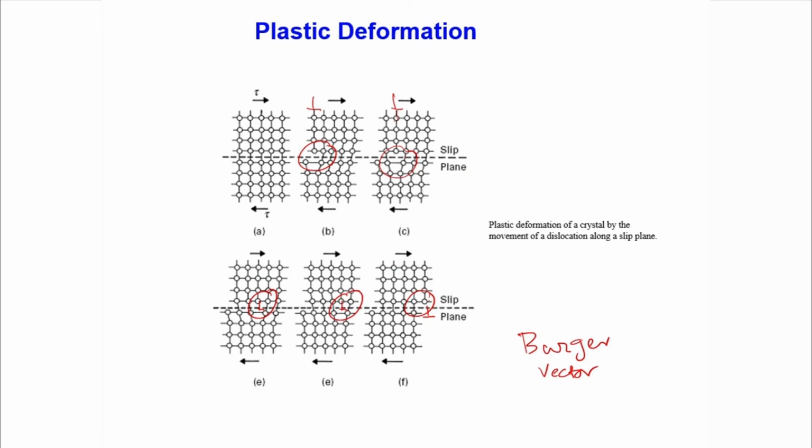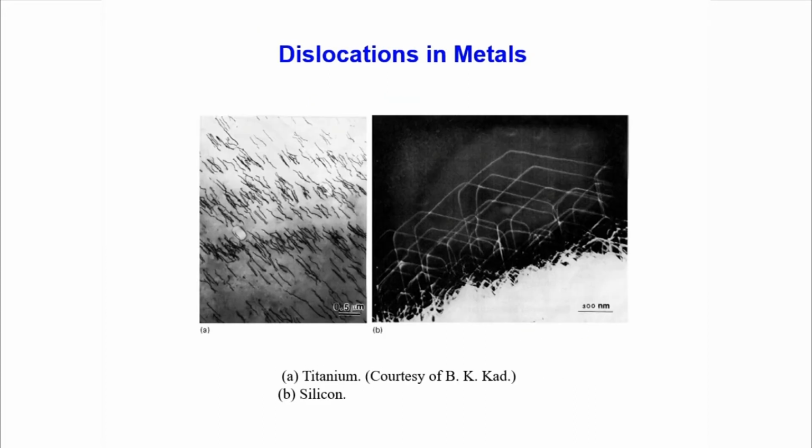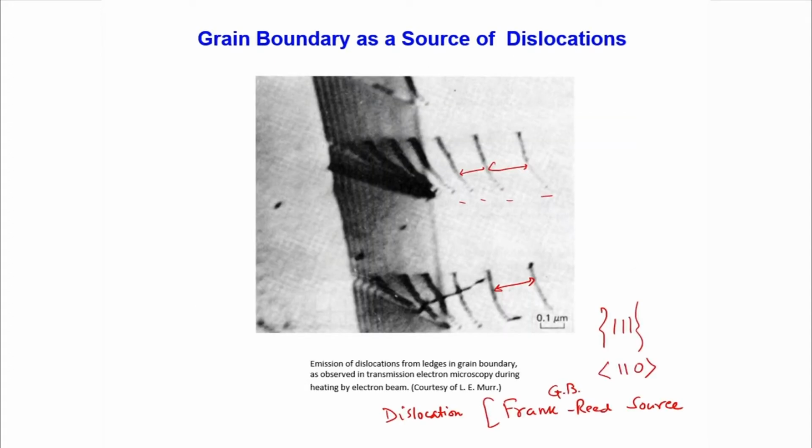Well, as we said, in nanocrystalline materials or in normal materials, plastic deformation, which happens because of dislocation motion, is predominantly observed. That is the mode of deformation in these materials as compared to the amorphous materials. And dislocations are seen under TEM. I am showing this picture again and again, with titanium and silicon, where this has been observed. Similarly, it has been observed in ceramics also.